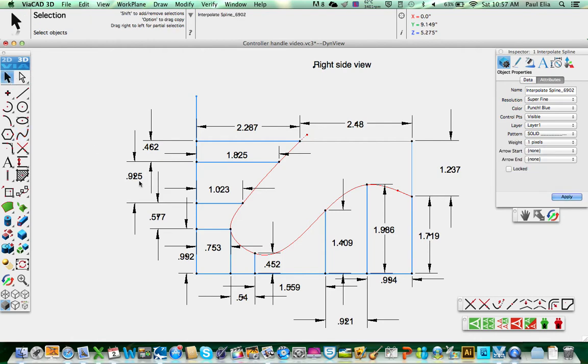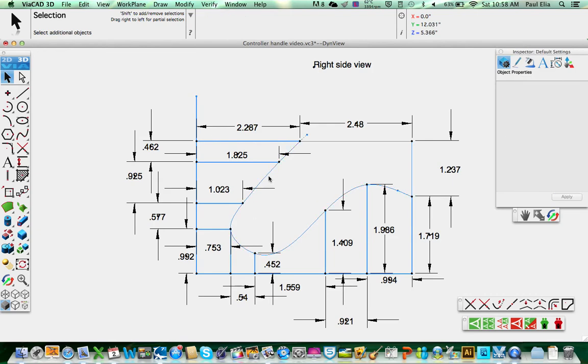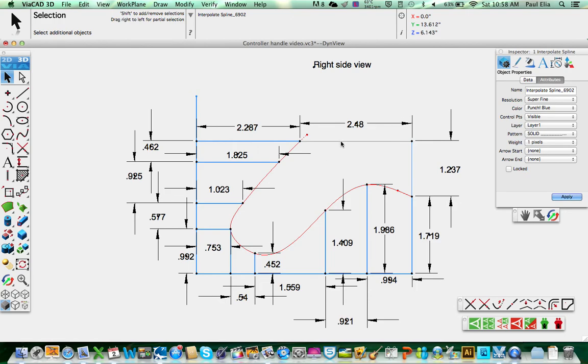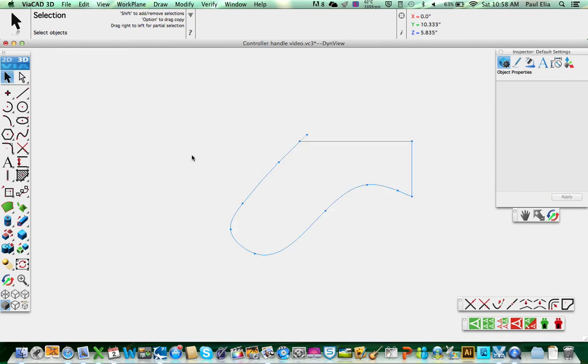I've got my profile now, and what I want to do is just leave the curves I want. I could do it this way, but the easiest way is hold down the shift key, and click this one, this line, turns color, this line, and this line, and go down to here. You can see it down there, do show only. So now I have just that. Now I've only got 3 items on the screen, and they're connected.